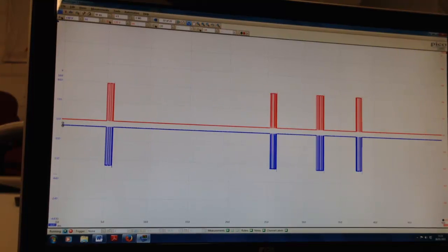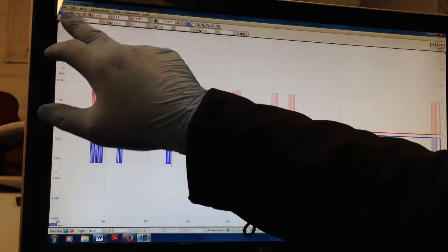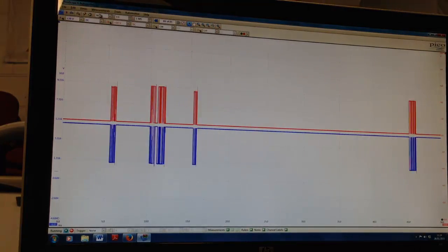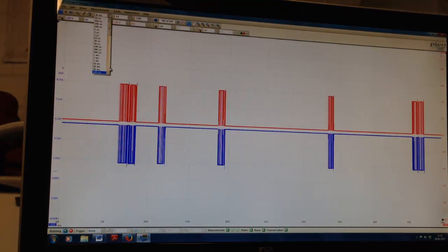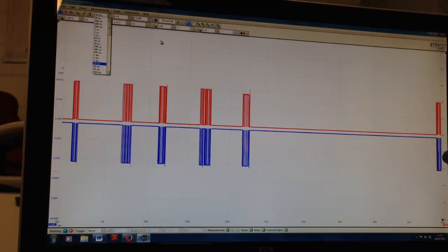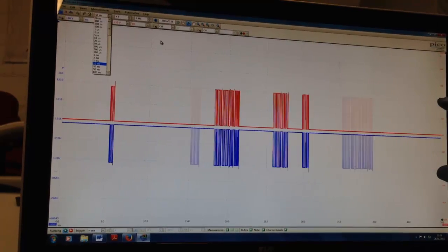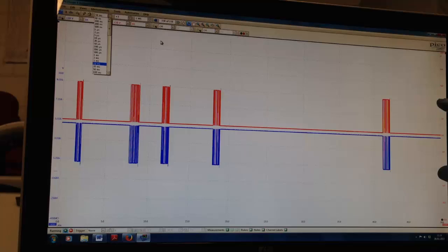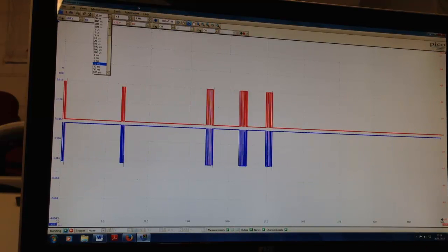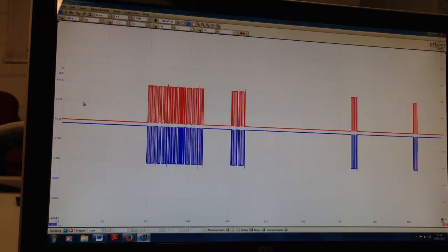We're not quite sure which way we've got connected up, and obviously it would be good if we had an issue with one of these or the other, we could have a look. So we set a 10 volt DC signal, a 50 millisecond time base, how it came on by default. We can zoom in there a bit and take a look, but what we know, without getting too excited, is it looks like we've got a signal of 0 to 4, 0 to 4, so body network, and the data messages at this level look to be okay. There's no short to positive, no short to ground, and they look like each other.